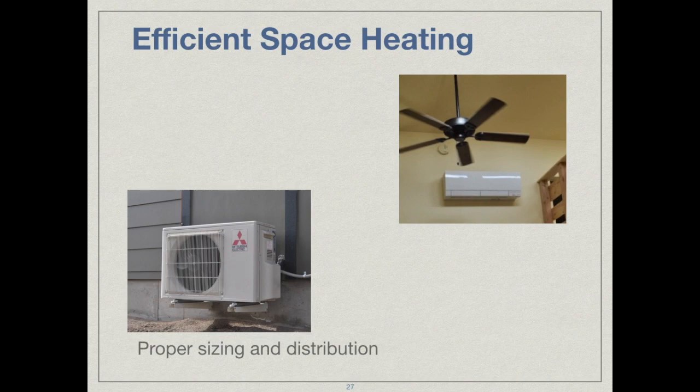One of the issues with heat pumps, the mini splits especially, is how do you distribute the heat? If they have a single indoor head, then it's a little bit difficult for that heat to go into the other parts of the building. There are a couple of things about this. If the building shell is super insulated and very tight, a little bit of heat goes a long way, and you won't really have as much problem distributing the heat, because the building will tend to equalize in temperature pretty well just from a single head.